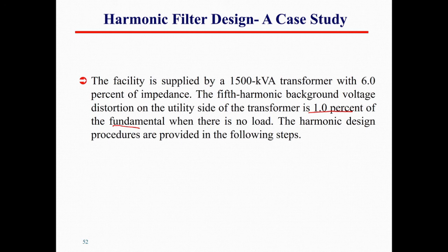Okay, so also what we have over here is a transformer that feeds the load, as we said. This transformer will have 0.06 per unit impedance, and it has S of 1500 kilovolt ampere.